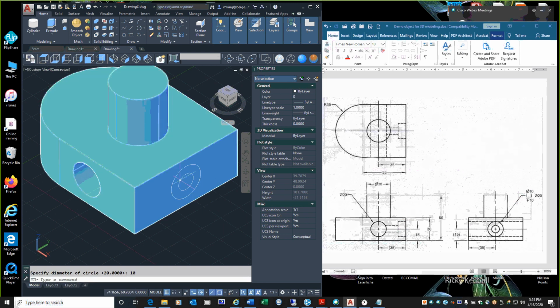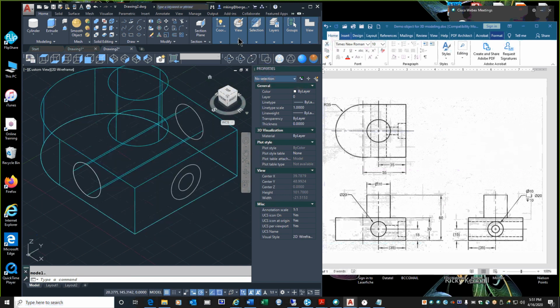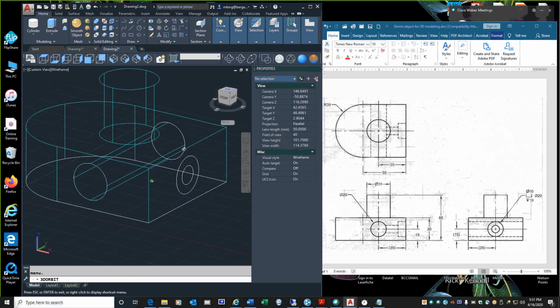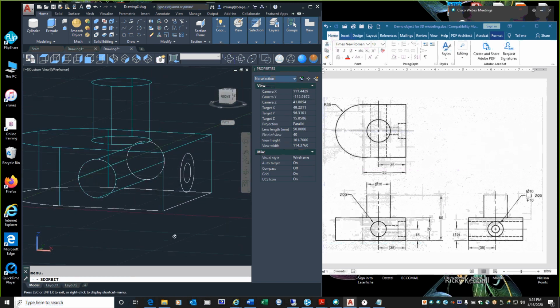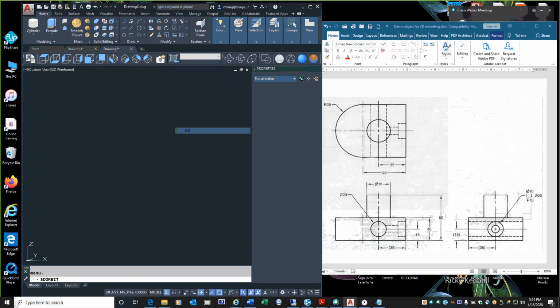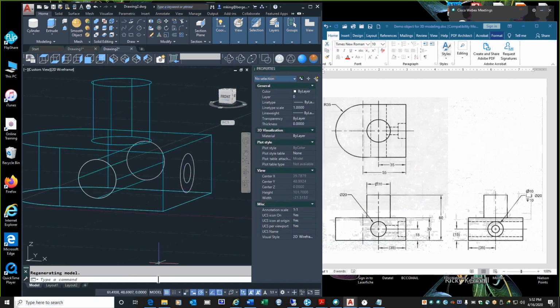What I need to do is press pull this in, but not all the way through. I just need to press pull it in as far as this hole here. I can't see the depth of that, so I'm going to switch back to 2D wireframe and orbit around a little bit more to the side here. You get a better feel for the depth of that. So 2D wireframe, and I orbit so that I'm around the side.